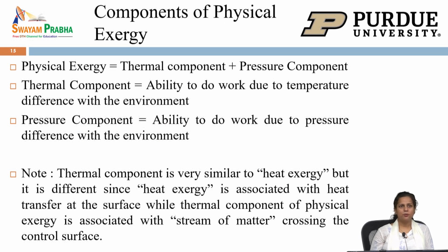So in review, physical exergy has both the thermal component and pressure component. Your thermal component is the ability to do work due to temperature difference with the environment. Pressure component is the ability to work due to pressure difference in the environment. And thermal component is very similar to heat exergy. So we have talked about heat exergy, that whenever you have a heat exergy transfer, there is some exergy or work available in that particular state.